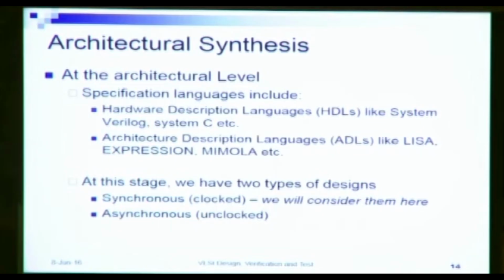You can describe the pipeline stages, you can describe the structure of the ALU at a much higher level than Verilog. The output of these languages will be another Verilog or VHDL code. You can also describe using architecture description languages like LISA, EXPRESSION, MIMOLA, etc.